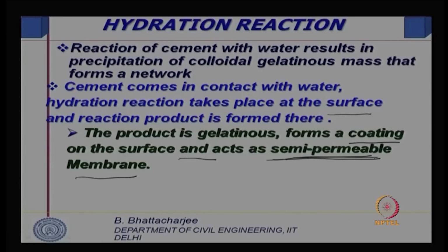Now, on the grain side of this semi permeable membrane, there is more concentration of the solute, that is the cement itself, and on the other side there is less concentration of the solute. So, when you have a difference in concentration across a semi permeable membrane, it gives rise to osmotic pressure. We will come to that sometime later on, at the appropriate time.